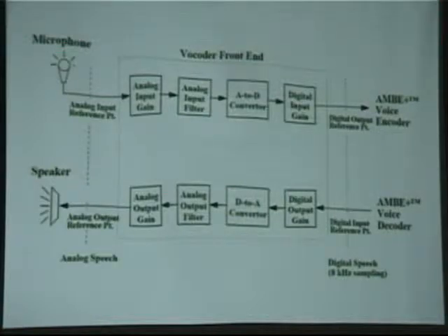Your cell phone, for example, uses a vocoder. They're not always the same. The two-way radio vocoders are a product of a company called Digital Voice Systems Incorporated, and it's a patented technology, but it has pretty much been universally adapted by the majority of the digital voice two-way radio type systems. The cell phones use other types of vocoders, adaptive multi-rate. They all have a fancy name for them. AMBE stands for Advanced Multi-Band Encoding.